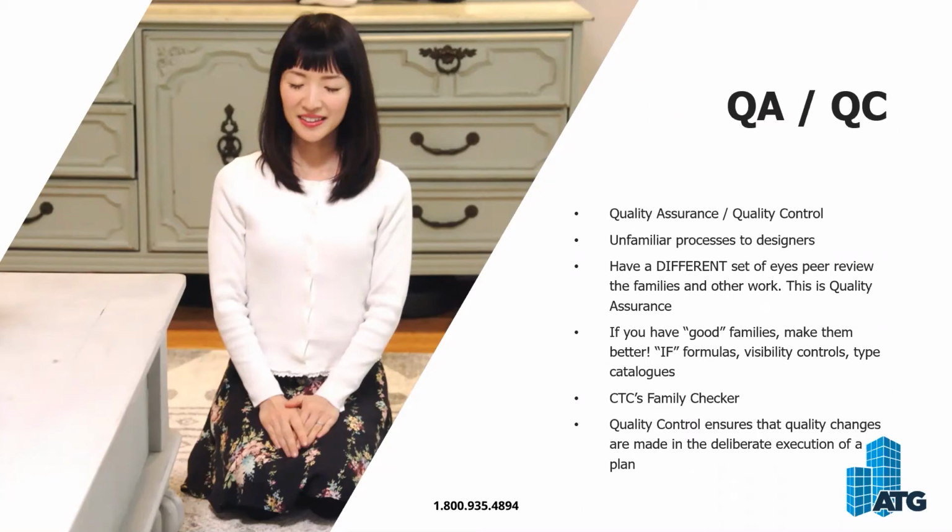They know how long it takes to troubleshoot a problematic family, find out if it's a geometry problem, a constraints problem, a parameter issue, a formula issue, and then try to resolve that. The fix normally is not that hard. It's the investigation and the testing that will sort of eat your lunch.